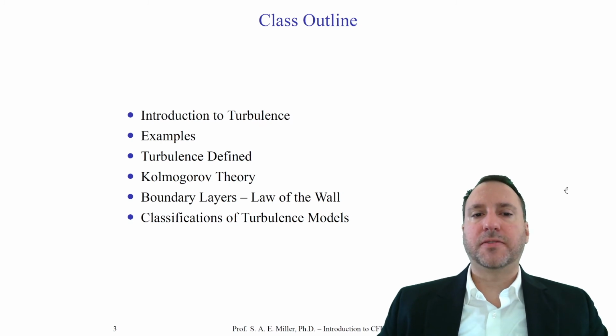We'll also look at a different class of flows, the boundary layers, which of course contain the law of the wall. We'll review this also. Finally, we'll look at different classifications of turbulence models and how they might be transitioned to CFD. These are not necessarily CFD models, but those that came out of theory many years ago. Yet today, the turbulence models we develop in CFD usually fall into one of these particular categories.